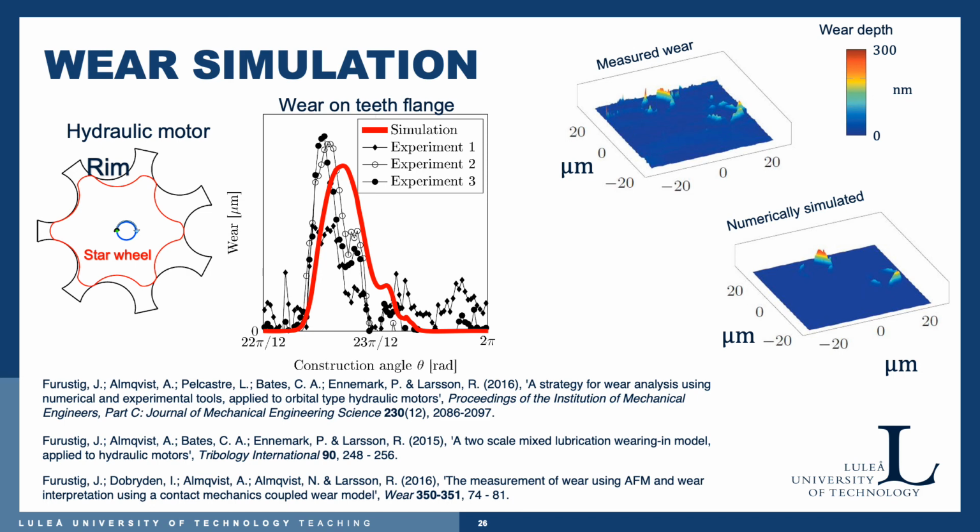Before he examined this hydraulic motor and adapted the wear model for that, he was doing a lot simpler, more fundamental types of wear experiments. So he took an indenter in our lab and made small indents in a surface, and then he wore that surface in one of our test rigs, and he measured the topography before and after, and found that the wear volume looked like this.